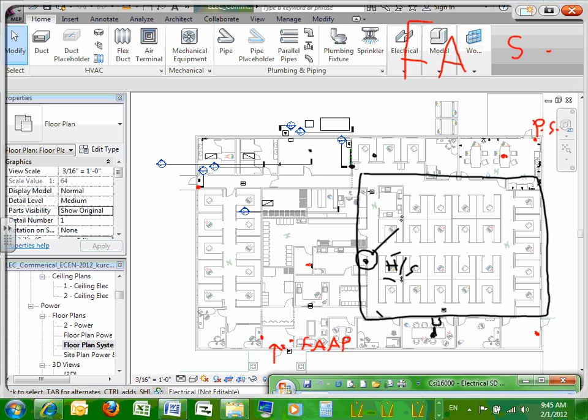They just send a supervisory alarm, and the owner would get a call saying your system is in alarm, supervisory only, which doesn't mean general alarm, so we didn't dispatch the trucks, but you need to do something. Then you, as an owner, would go to the building, walk in the door and see that your annunciator panel says dirty smoke detector in the mechanical room, and then you need to call somebody out there to clean that smoke detector and or replace it.